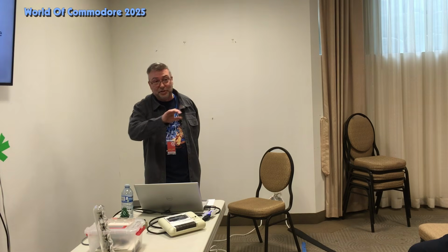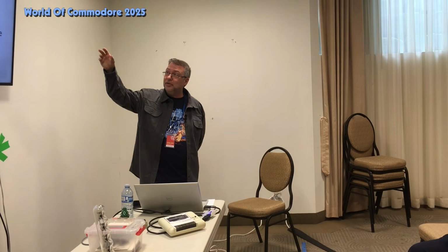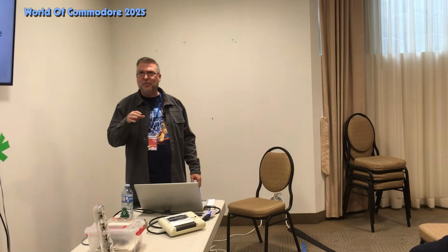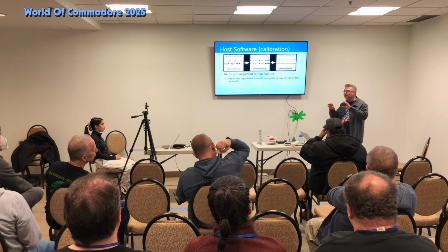I didn't go into the details because for this project, we only work at the very low level, just for the pulse itself. But when you start checking the type of pulse, the 0, the 1, and the synchronization, they built a whole protocol on top of that, where they have blocks, header, the data, some error correction on top of it. Like I was saying, they also duplicate each block. You can find the documentation on the web about this. I think it's around 180 bytes per block of data and some padding for the header and error correction.